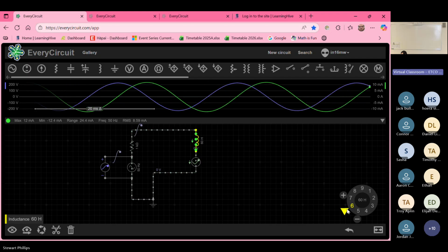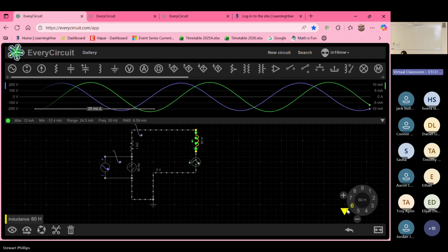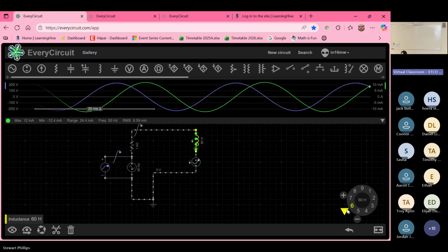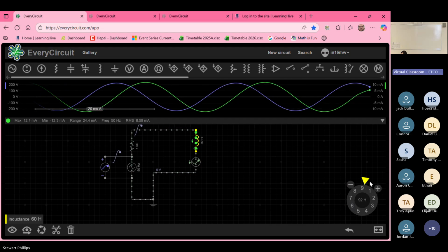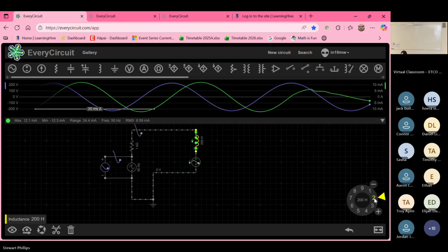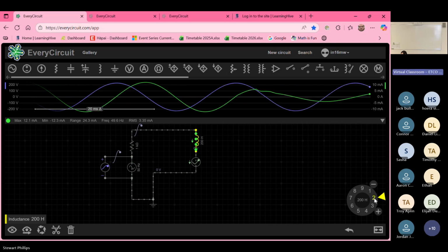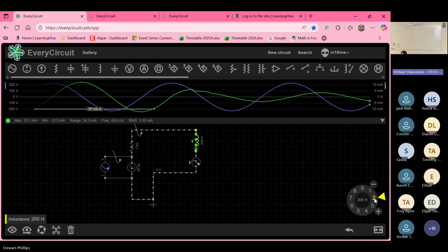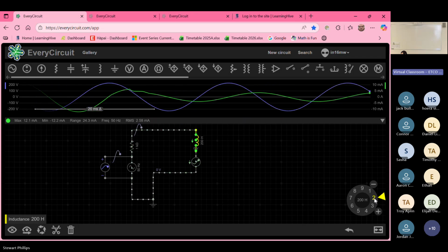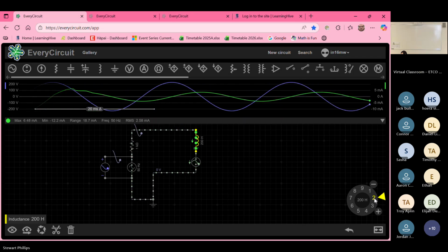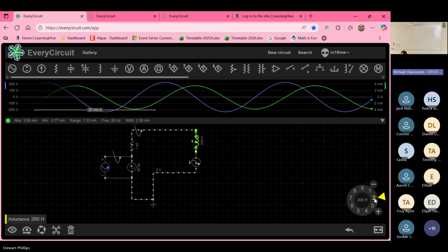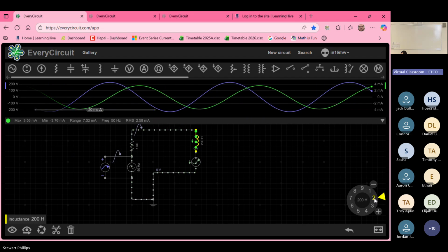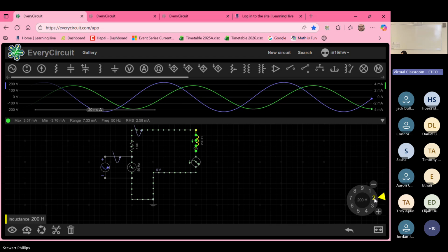Now it's back up. You can see how much further behind it's lagged. But then if I increase it again, you can see there's a slight delay because of the increase. So the current has dropped a little bit. But you can see it's slowed down even more behind. So eventually we get to magnetic saturation.